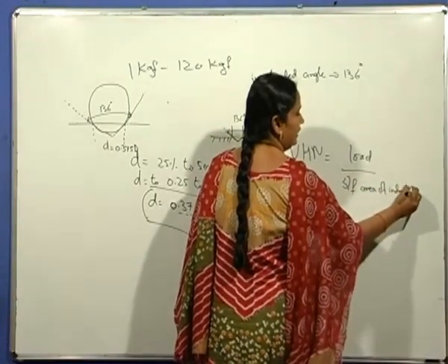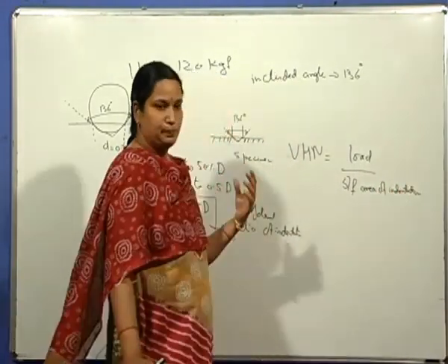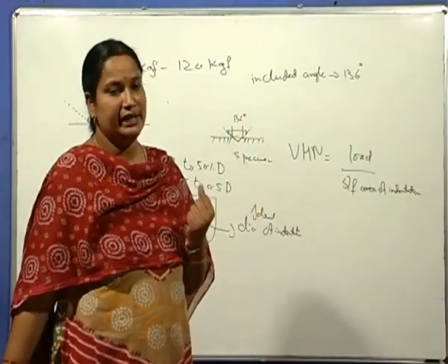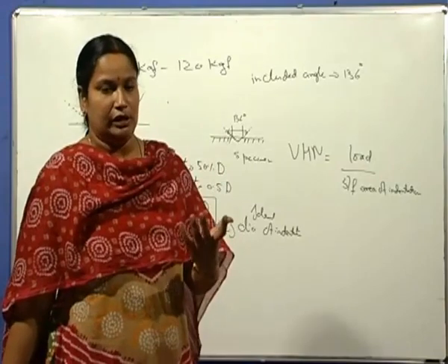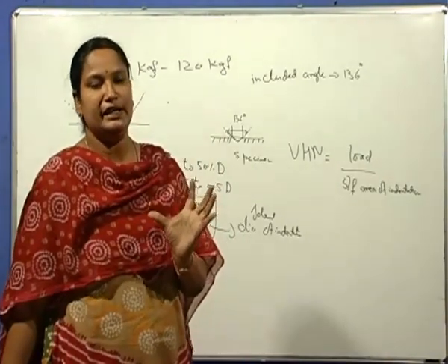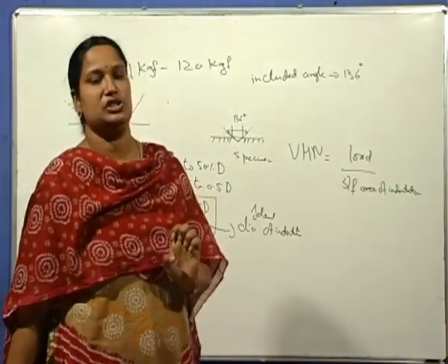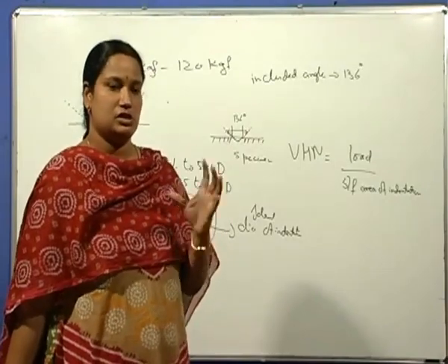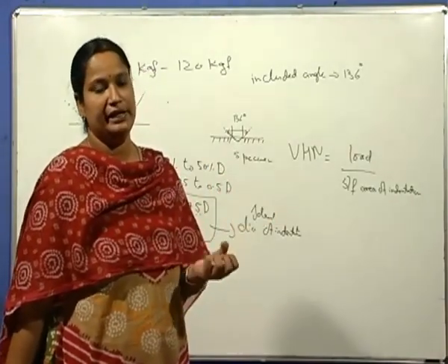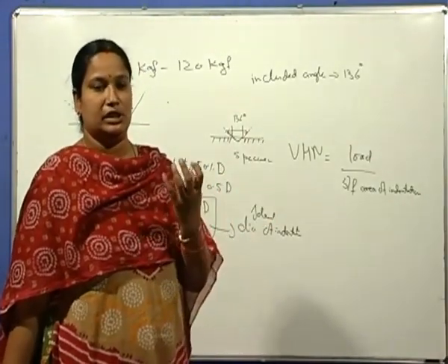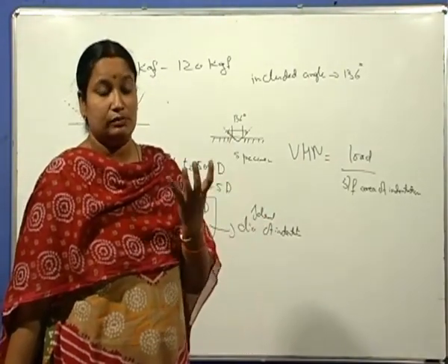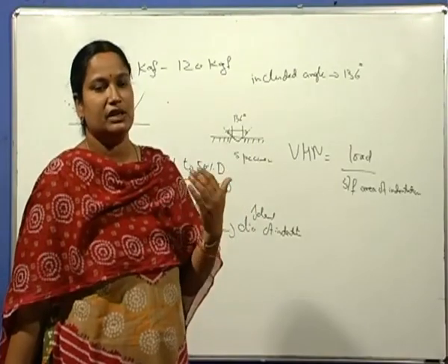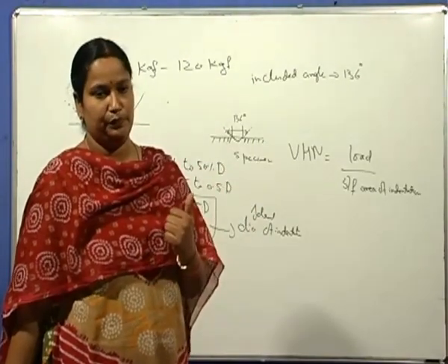The one advantage of using this pyramid shape indenter is that even with increase in load, the shape of the indentation does not change, whereas for the case of spherical ball indenter, the shape cannot be maintained constant, that means the shape will change with increase in the load.